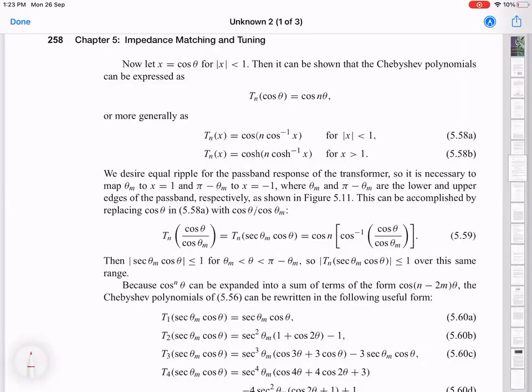So the reason for this example is that there is this component. Some of you have worked with PLC cables and things like that. There's this thing called a T junction. You use that to send signals to multiple places. Depending on what you're doing, it can be a very bad idea, because you are exactly doing this configuration. You're connecting two 50 ohm lines to one 50 ohm line. You're going to get reflections at those points.